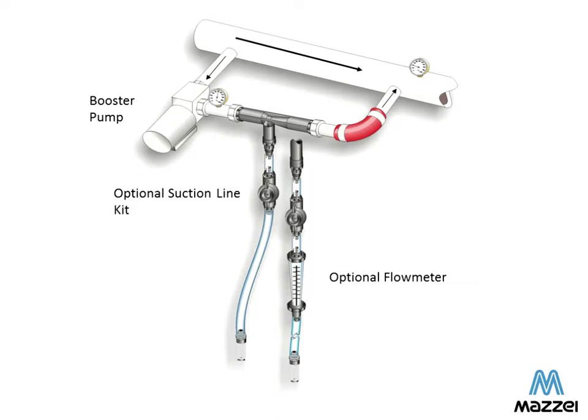Now in this case, it is most advantageous to choose the smallest injector that will give you the suction capacity that you need. You want to minimize the horsepower that you use in this booster pump here.